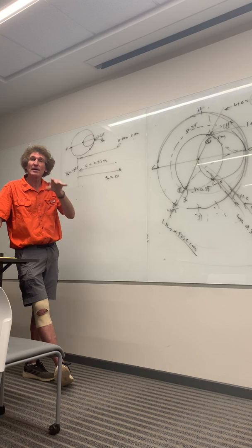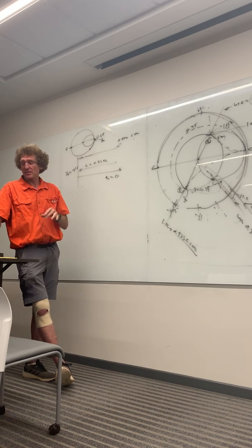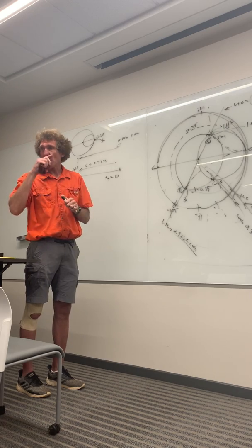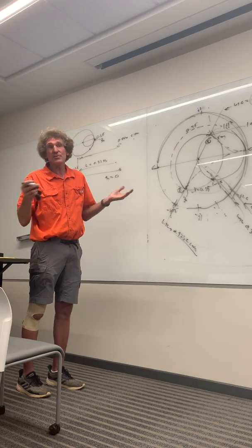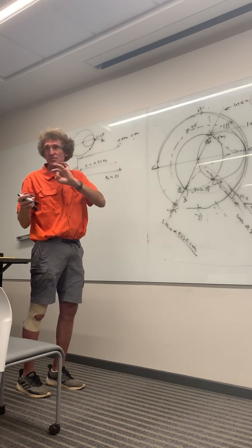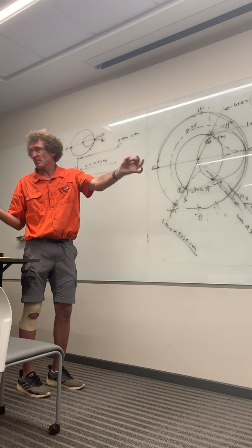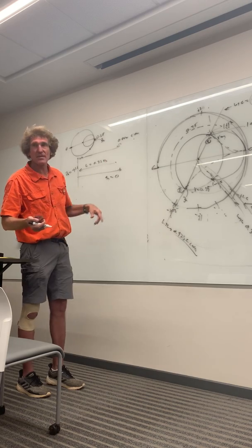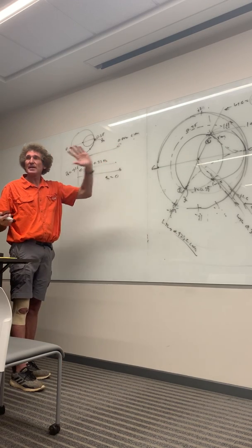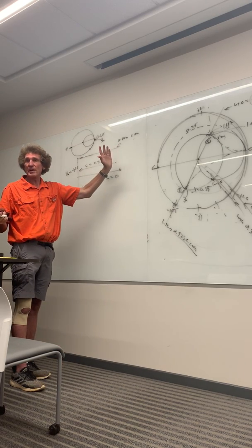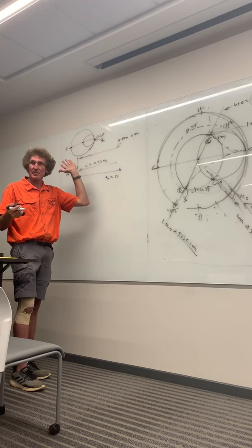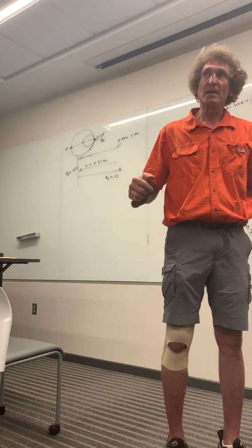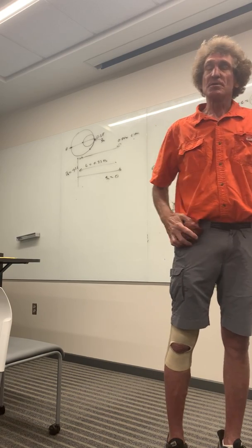That's how come I never ever tell people to use that unless there's an overwhelming reason for it that I can't think of right now. So I don't ever tell people to do that. But they do it sometimes when you're dealing just with transmission lines that are coax cables. Sometimes they'll do something like that. I hate that because it also means it's susceptible to stuff. That's a little antenna there. So it introduces a new form of EMC problem because now you can get signal coming in there too. All right, that's basically impedance matching using series elements.